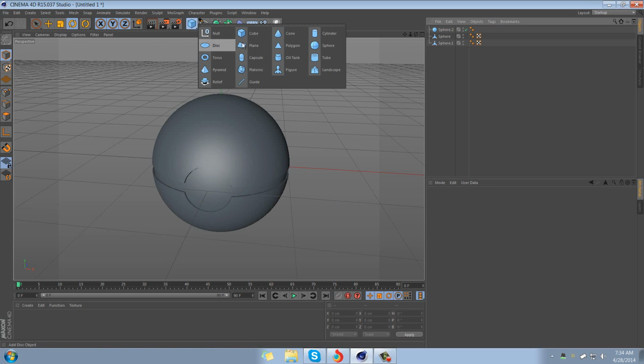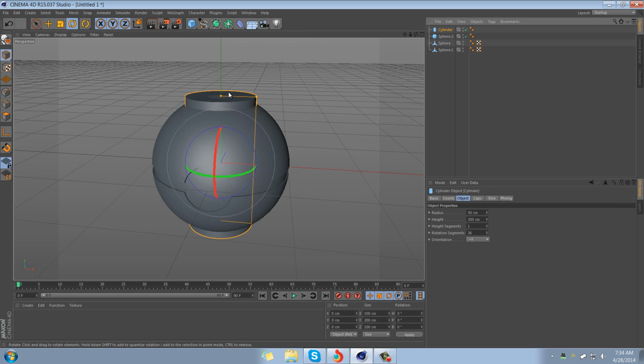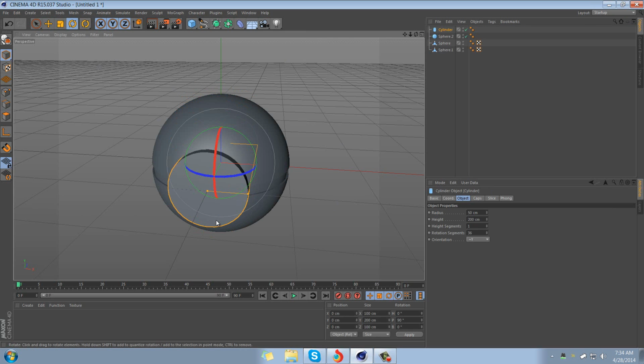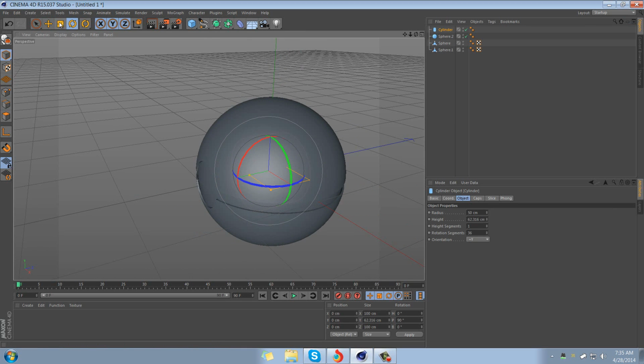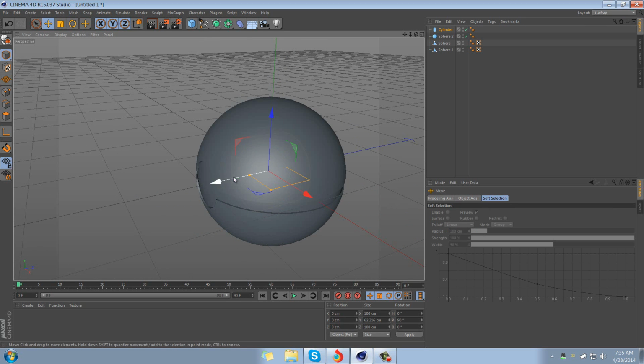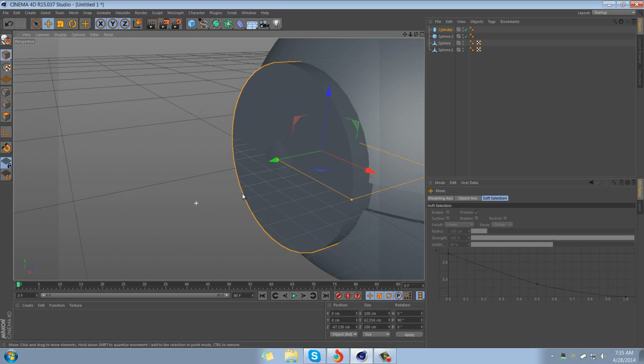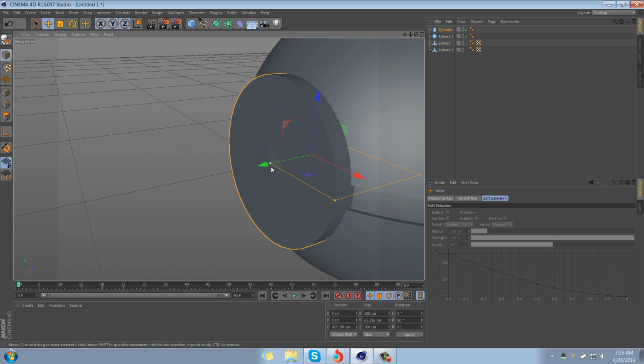And now, once this is here, we're going to need to come up and spawn another cylinder this time. And we're going to rotate that straight down to 90 degrees. Grab the little square pin right there and shrink it in real tiny like this. The movement tool once more to drag it out. So if I zoom in here, you can see this little diamond shape.